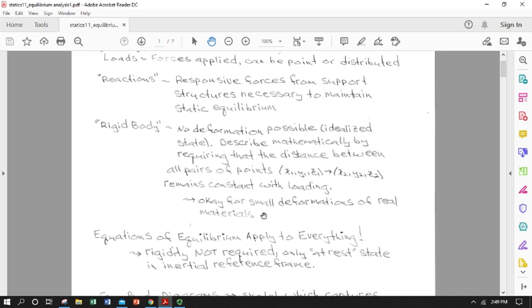In the real world, of course, nothing has an infinite modulus. Even the most rigid materials like carbon fiber in tension or certain ceramics, everything has a finite modulus in tension, compression, and shear. So rigid bodies are ideal, like ideal fluids. They don't really exist. However, if we are looking at very, very small deformations, we can approximate most things as rigid bodies. So basically, it depends on the load versus the modulus. And in most applications the deformation doesn't matter, if you plan for it.